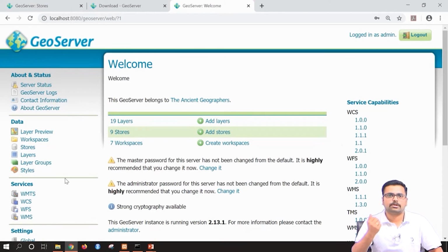Task 1 of our Geoserver is to publish a vector file into the Geoserver interface. In the previous session we have seen that we had various vector layers. So let us try to bring in some of the vector files into the Geoserver. In the previous sessions we have seen one particular vector file wherein we had clipped the road according to the Mysore district file. So how to add that? Before adding the vector, first we need to create a workspace.